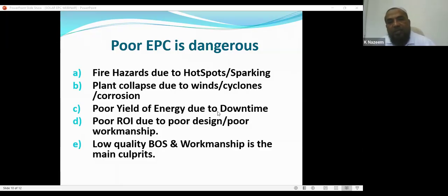Then he explained to the customer, sir, batteries are good, UPS is good, but the problem is the design problem. The cable from the UPS to the batteries is 10 meters, and for every meter, there is a drop of 0.1 volts. So what happens? 0.1 into 10 meters is equal to 1 volt. You know that the battery standard voltage is 12 volts.